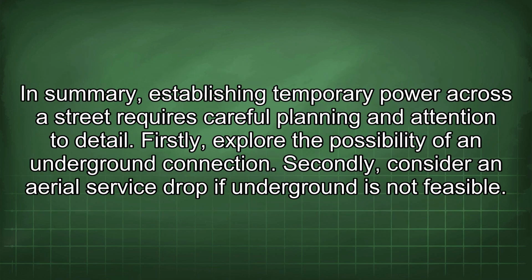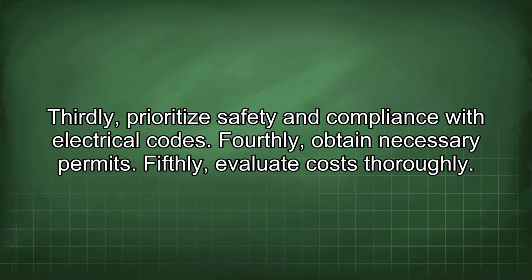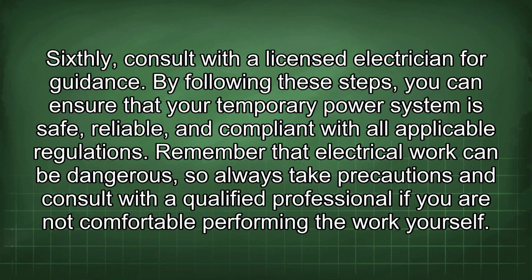In summary, establishing temporary power across a street requires careful planning and attention to detail. Firstly, explore the possibility of an underground connection. Secondly, consider an aerial service drop if underground is not feasible. Thirdly, prioritize safety and compliance with electrical codes. Fourthly, obtain necessary permits. Fifthly, evaluate costs thoroughly. Sixthly, consult with a licensed electrician for guidance.